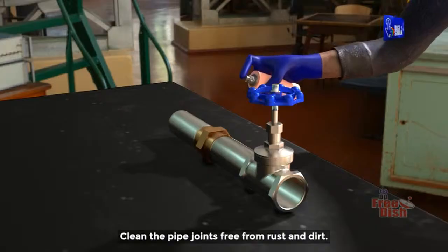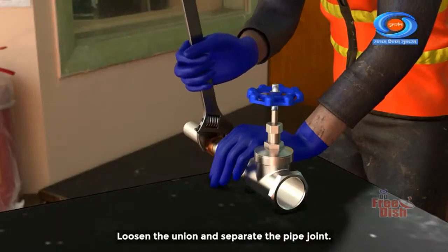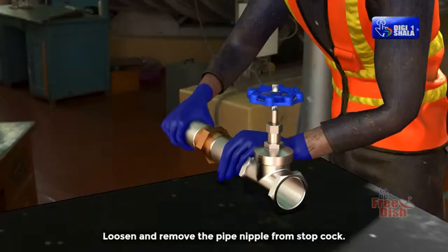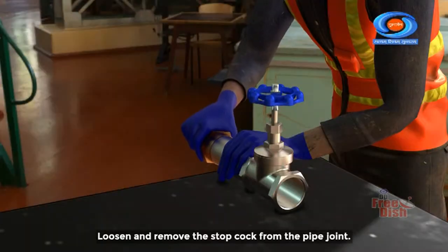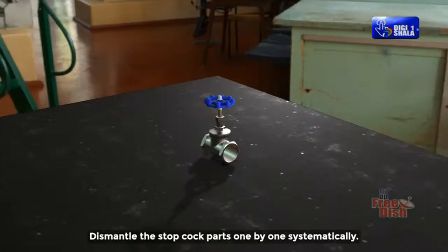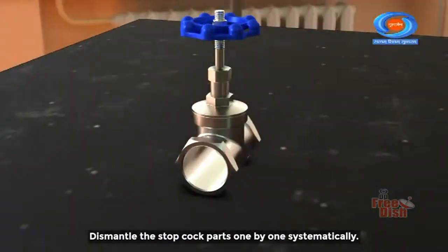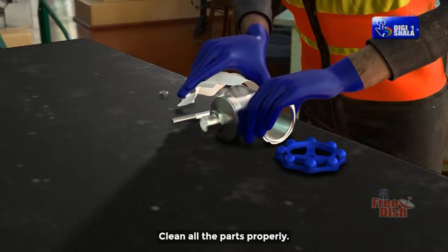Clean the pipe joints free from rust and dirt. Loosen the union and separate the pipe joint. Loosen and remove the pipe nipple from the stopcock. Loosen and remove the stopcock from the pipe joint. Dismantle the stopcock parts one by one systematically. Clean all the parts properly.